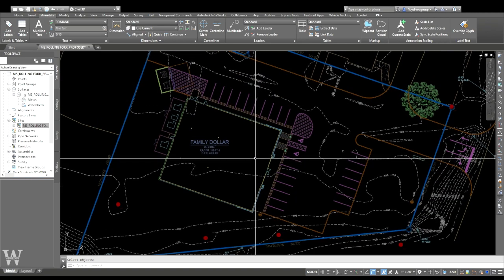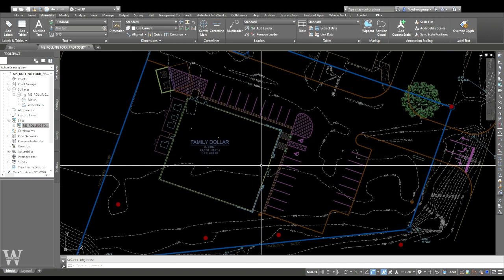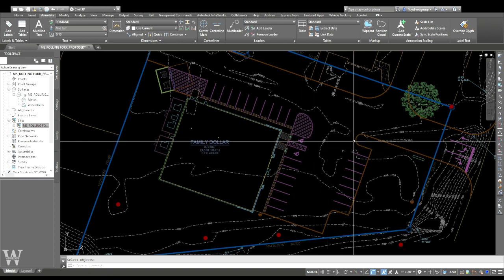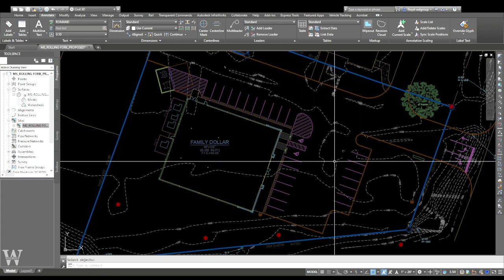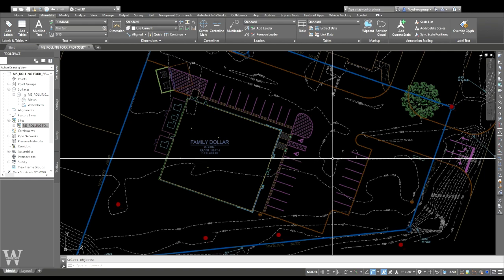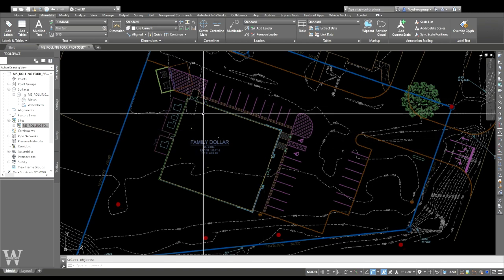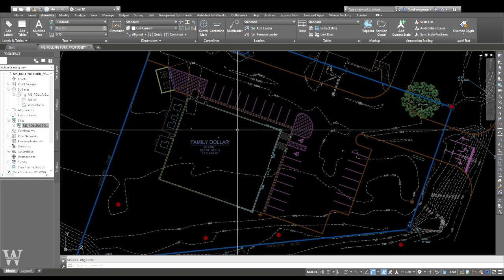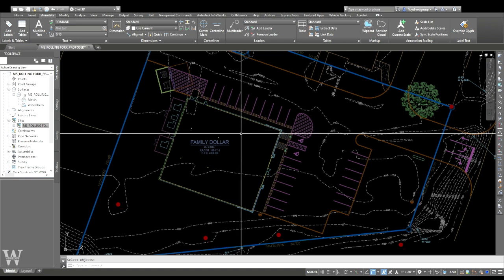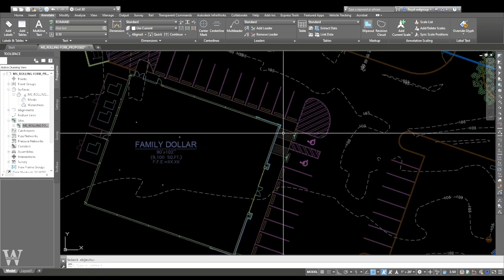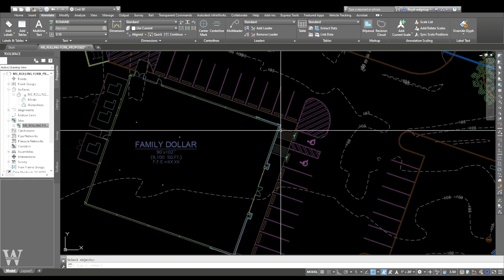When you try to use grading objects and corridors and all that on a small site like this, it's a pain, because this site goes that way and then it goes that way and then it slopes that way, and those things aren't made to do that. I wish Autodesk had come that far, but they haven't. One thing about feature lines is they're not really easy to modify. They don't like to break and trim very easily. Just cumbersome. They want you to click 4 times for stuff you can do at 1 time.